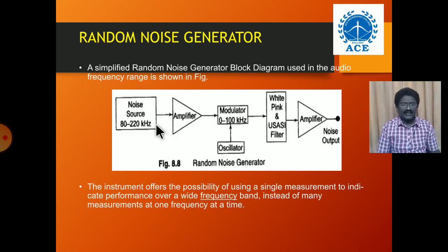The power density spectrum tells us how the energy of a signal is distributed in frequency, but it does not specify the signal uniquely, nor does it tell us very much about how the amplitude of the signal varies with time. The spectrum does not specify the signal uniquely because it contains no phase information. A spectrum gives an idea about all the color wavelengths and frequencies, like that.